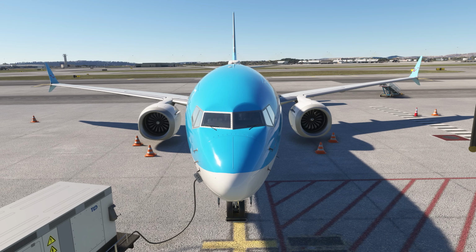The engines, which are brand new, have similar qualities to how the CFM56 reacts, these CFM LEAP 1Bs as well. The pitch settings are the same. The thrust settings, though, are considerably lower, about 8% for each phase of flight. But the same flying qualities exist in pitch, yaw and roll.